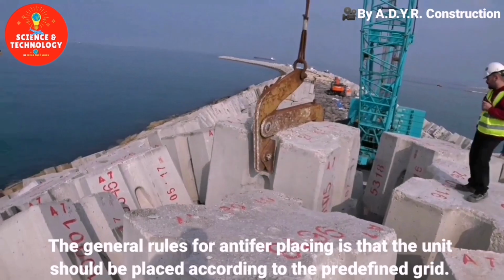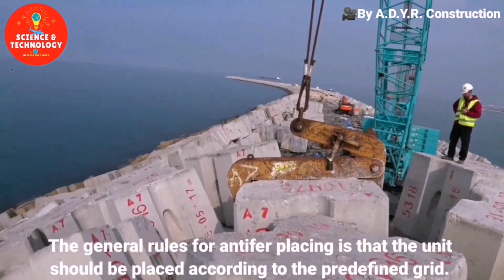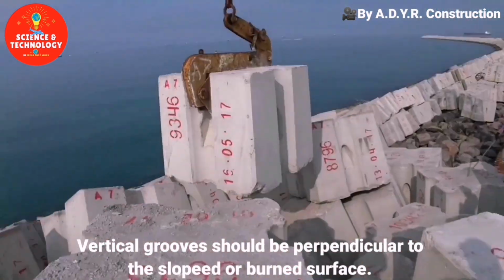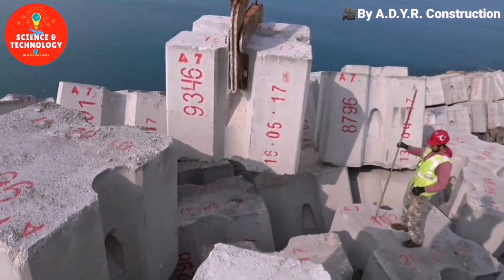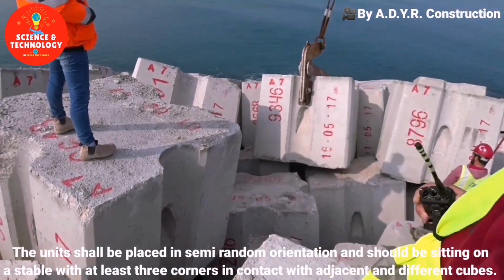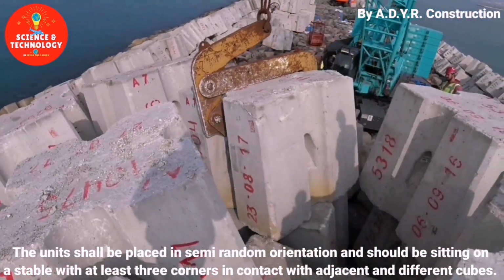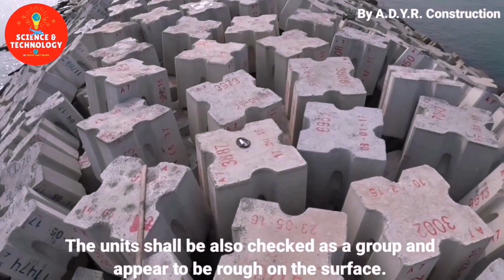The general rule for Antifer placing is that the unit should be placed according to the predefined grid. Vertical grooves should be perpendicular to the sloped or burdened surface. The units shall be placed in semi-random orientation and should be sitting on a stable base with at least 3 corners in contact with adjacent and different cubes. The units shall also be checked as a group and appear to be rough on the surface.